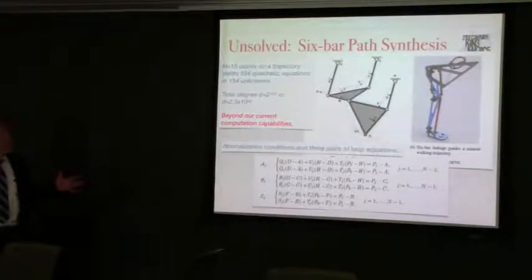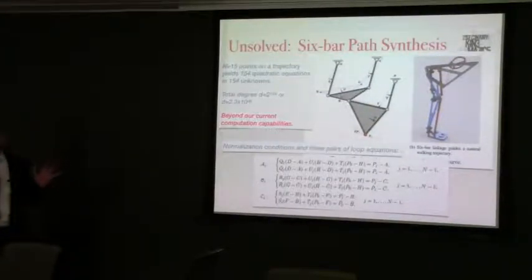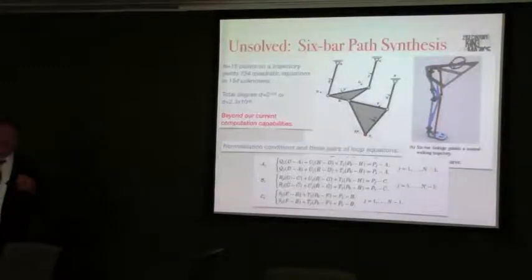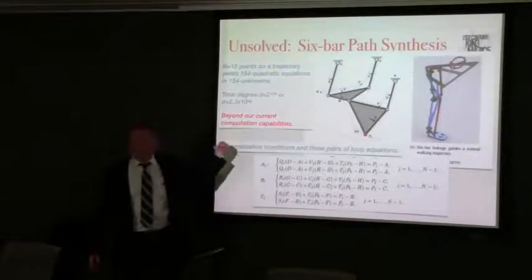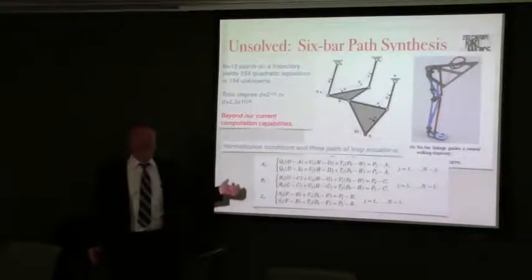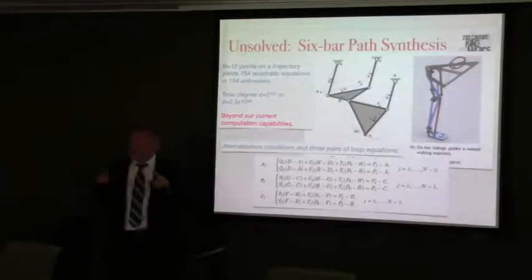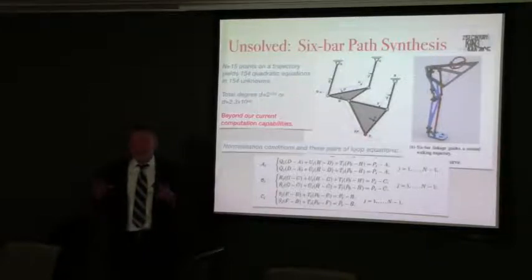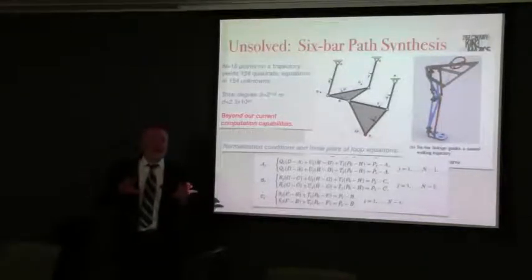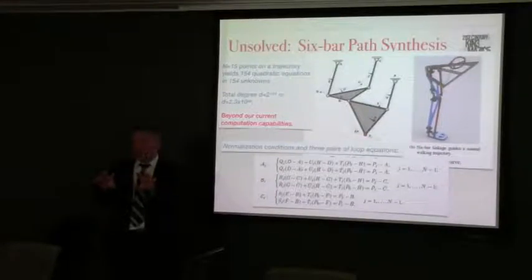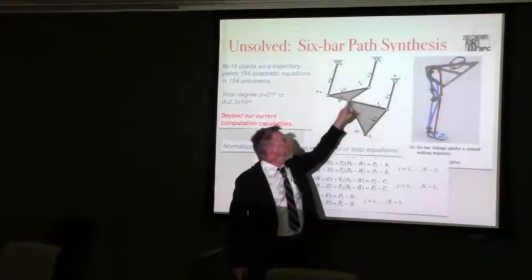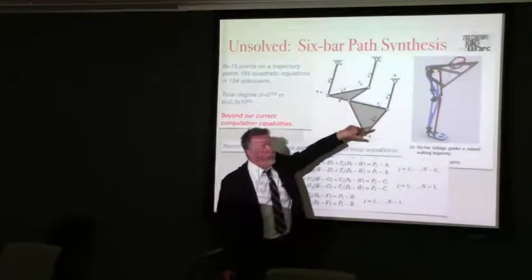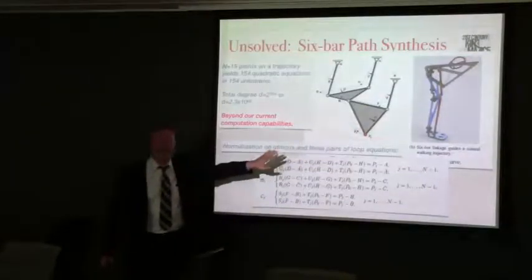What I'd like to now show you is the simplest of the unsolved problems that we have in kinematics. This is nothing more than taking that problem of Freudenstein's and generalizing it to not a 4-bar linkage, but a 6-bar linkage. The 6-bar linkage differs from the 4-bar linkage only in that there are 2 loops rather than 1 loop. So you have 2 loops here. There's a 3rd loop when you sort of include the 2. All 3 loops are linearly dependent.